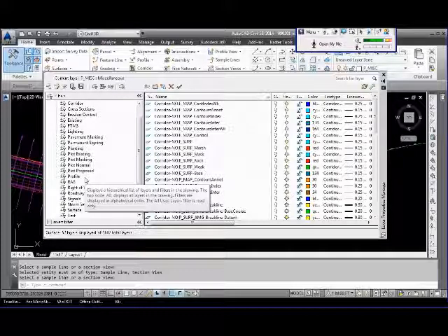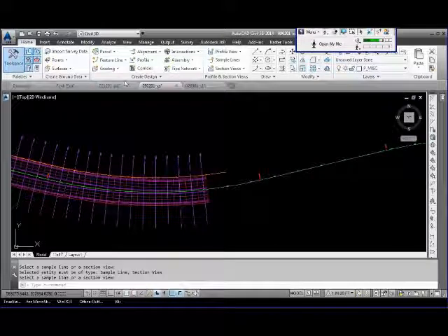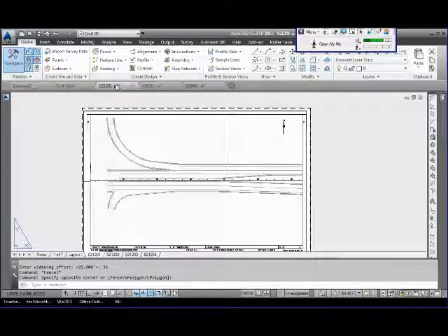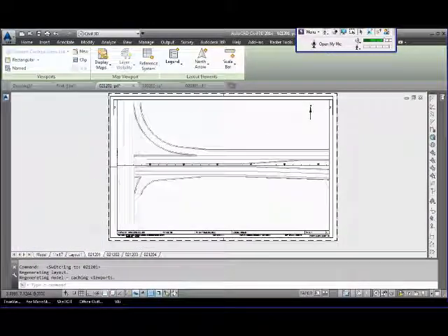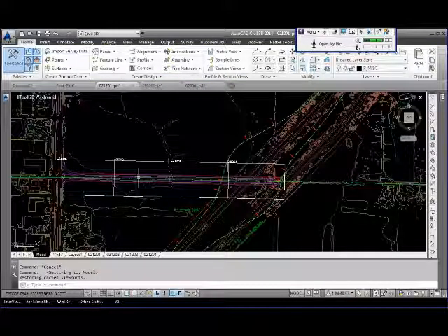If you have the layer manager open and you have a ton of references, that's going to take a while. And it actually even flipped to a different drawing from the background. This is something that you can really control by closing the layer manager. So I'm going to jump back over to my plan detail. So it did go to the sheet. Remember how long it took for me to get there? I have the layer manager closed. I can pop over to model.